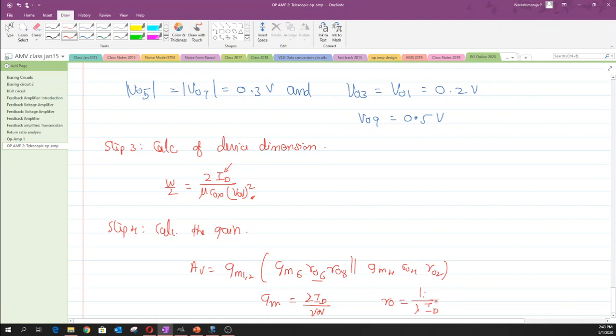Okay, yeah. So now what basically would happen when you evaluate all these quantities is that when you do the calculation, you will find that this particular quantity, which is the output impedance when we look towards the PMOS structure, has a value equal to 111K, whereas the NMOS structure will have a value which is 667 kilo ohm.